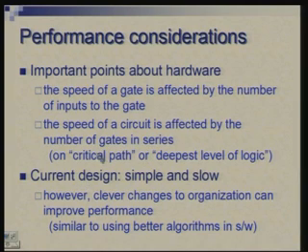So, in fact, this is really the motivation why we always try to express Boolean circuits as 2 level sum of product, or alternatively product of sum. You can have more complex expressions where there are parentheses and deep nesting of ANDs and ORs, but a sum of product form or product of sum form is most efficient from the point of view of this depth of logic consideration.